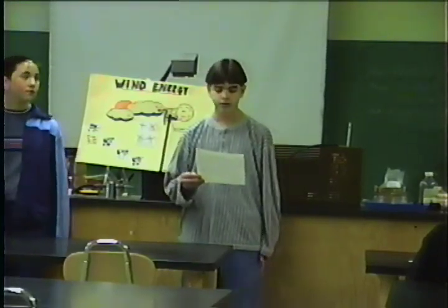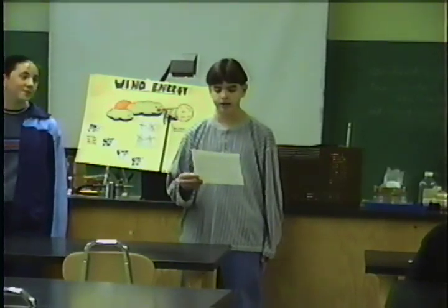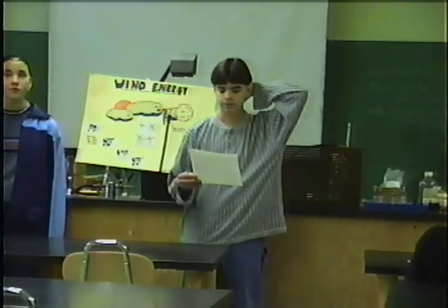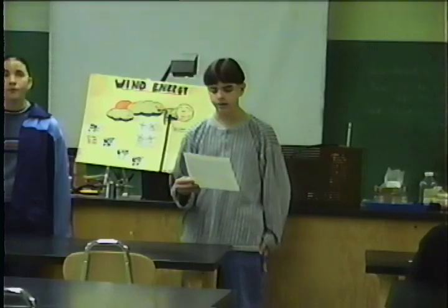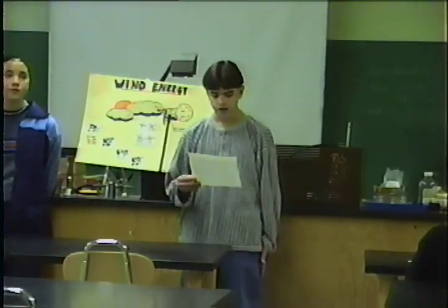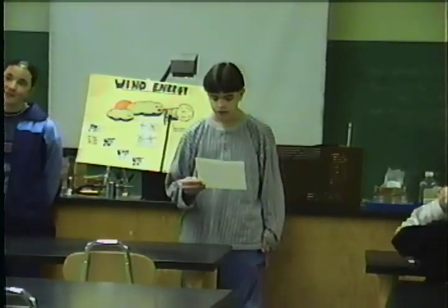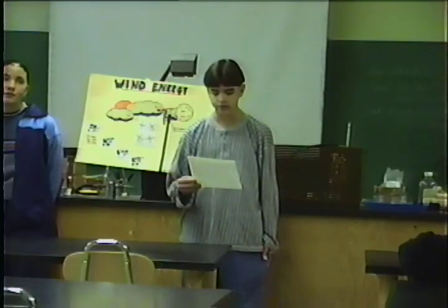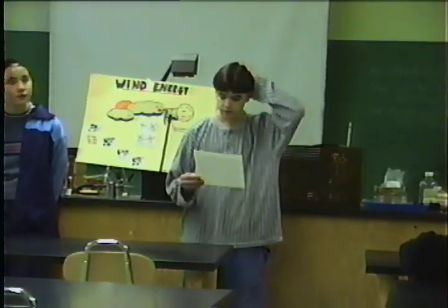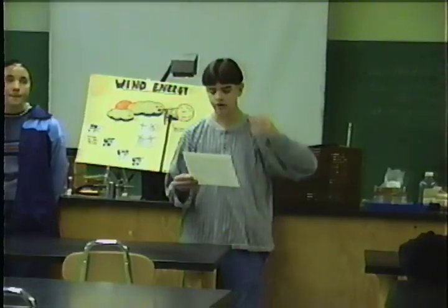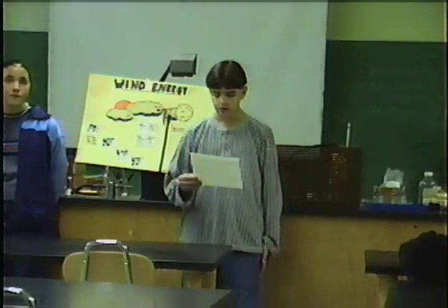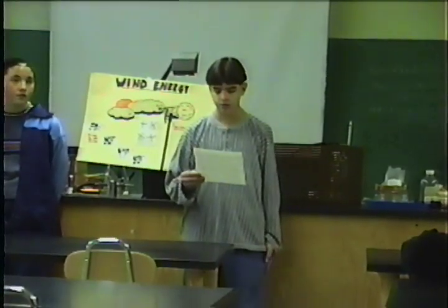The windmill is a rimless wheel that has vanes or blades for spokes. Like the water wheel, it's mounted on an axle. As the wind blows on the vanes, the wheel rotates the axle. This motion is then transferred by the axle to a drive shaft, which turns millstones to grind grain or other devices to perform work. Windmills can generate electricity or pump water.